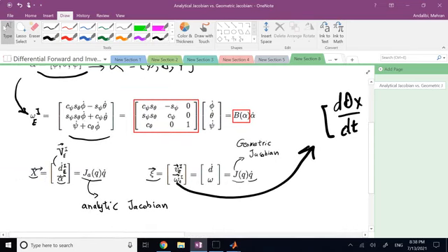The answer is yes. How? So take a look here. This vector that I found, the Euler angular velocities, combined with sine and cosine to give you the omega of end-effector in base, I can write as a matrix product. I can write it as a matrix of theta, phi, and psi. And since theta, phi, and psi we call alpha, I can call this matrix B of alpha.